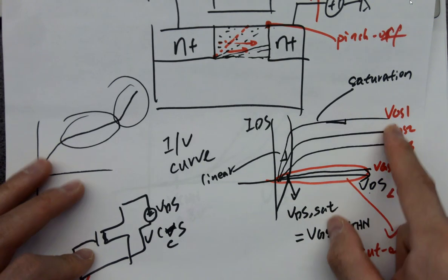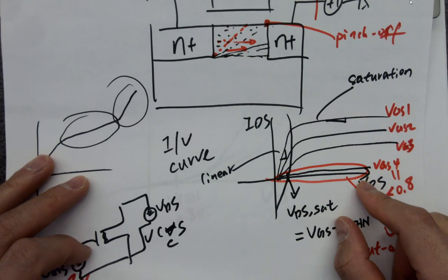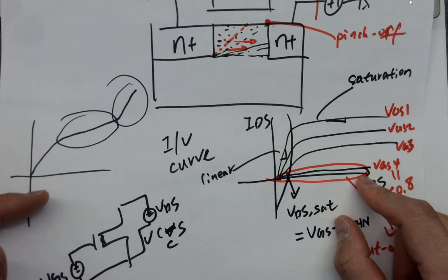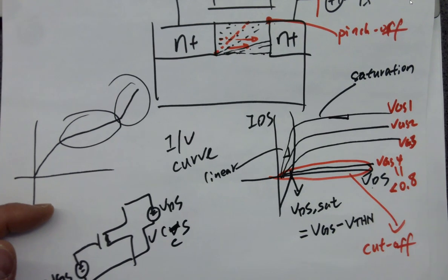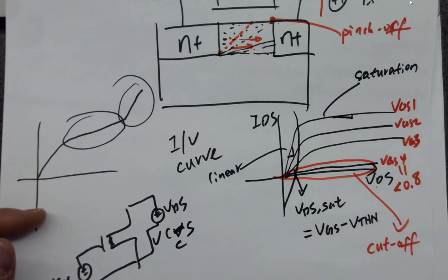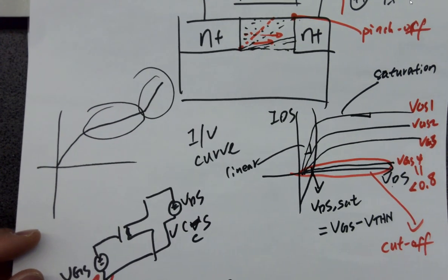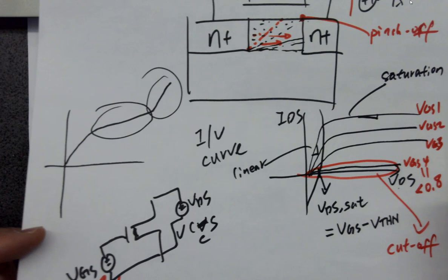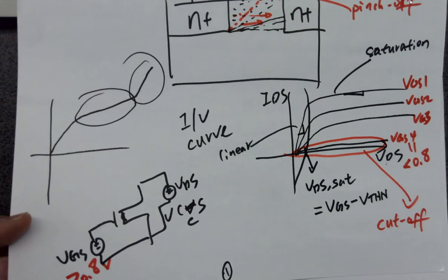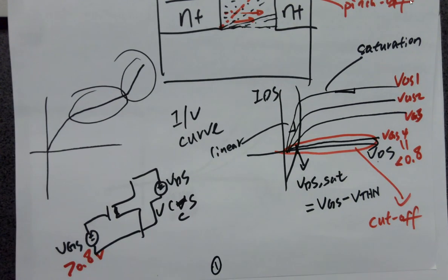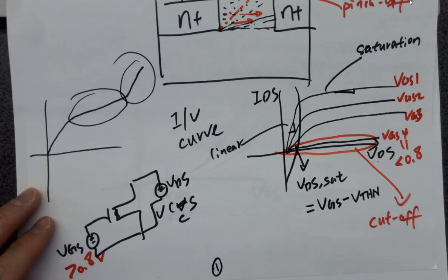So from here, even though I have a fixed VGS, I'm looking at VDS. But we know that no matter which one it is, as long as it's getting higher, you get a higher current, right? Doesn't matter, VGS or VDS. So higher VGS will give you a higher potential to drive more current through the channel. Higher VGS will open the channel bigger, and so you have more electrons in the channel. So whenever you apply the same VDS, it drives more current through it.